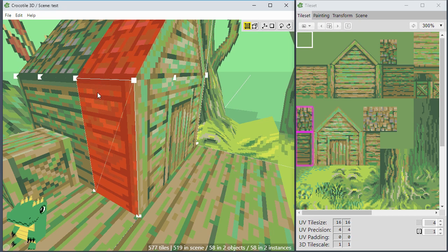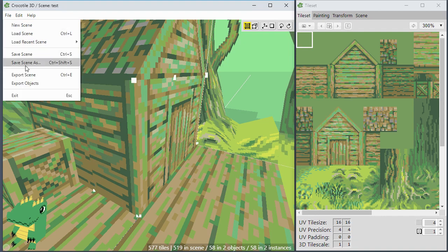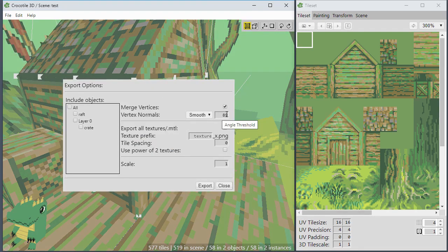Their angles are more similar to each other, so the vertex normals would get averaged together. I'll show you examples of this later. You can change this angle to whatever you want, but if you choose 90 degrees, there's a little bug with it, so I choose 89 instead. I still have to fix that anyways.